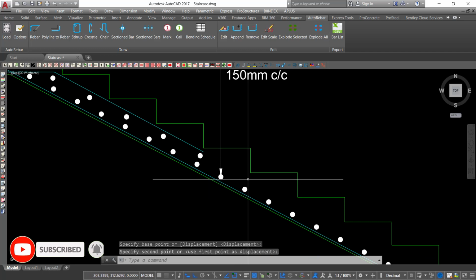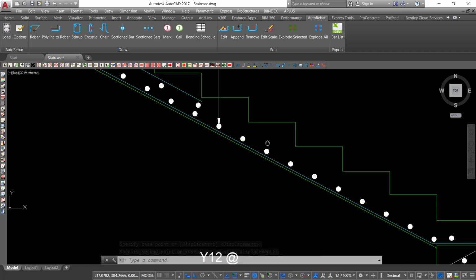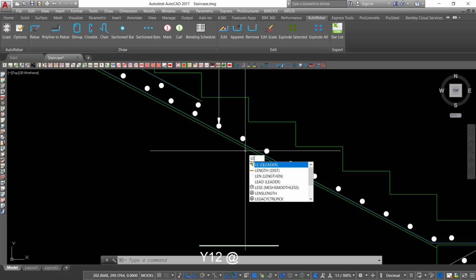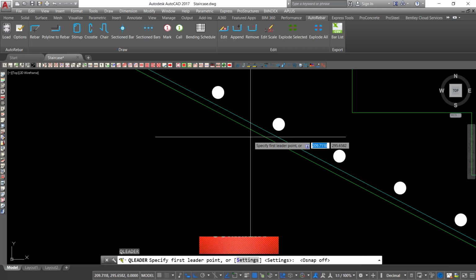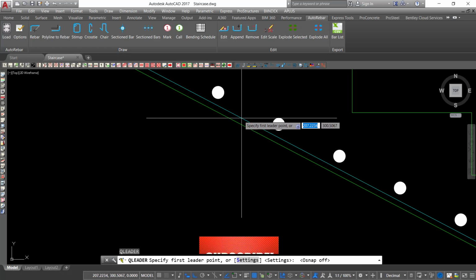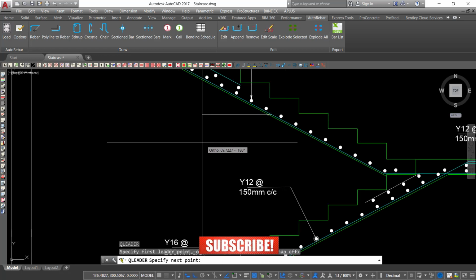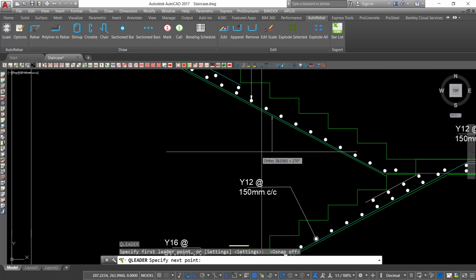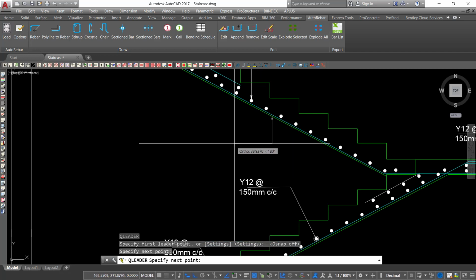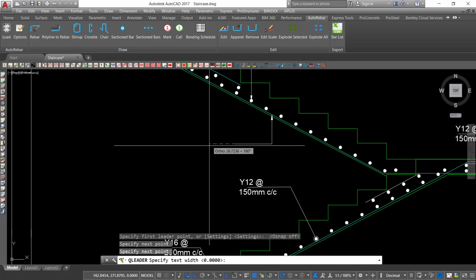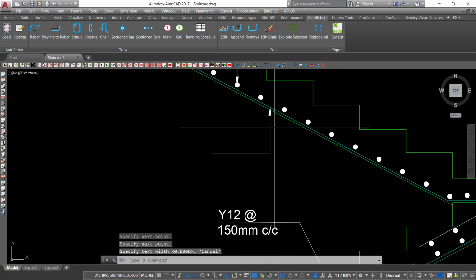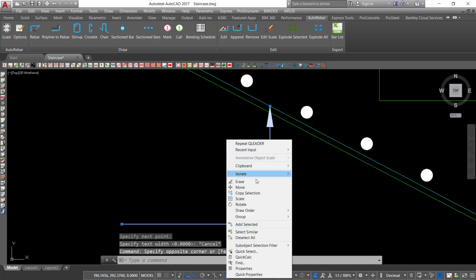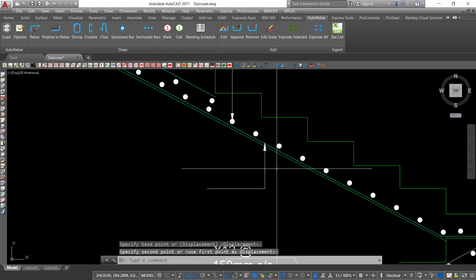We've labeled that. So remember, we're going to also highlight on this. Select, and I'll pick on this bar. Remember to disable the ortho mode or snap. So I'll drag it down, terminate it there, snap there, and don't enter, just press escape to terminate that leader. So select on it and drag it slightly inward.